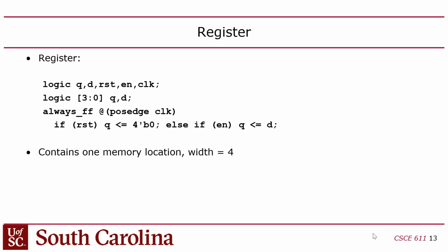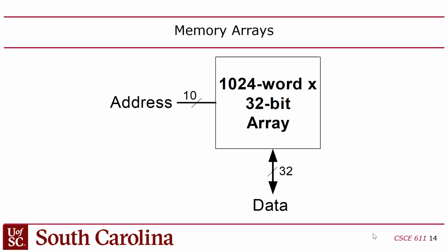Okay? But the switches are only 18 bits, and that register here is 32 bits, so you're going to have to pad it with zeros, unfortunately. Some students take the buttons, we have those buttons on the board too, and kind of piggyback them here. You can concatenate the buttons in the upper bits of this if you need to read the buttons as well as the switches. The lab sheet only requires that you read the switches. You guys with me? But you have 14 extra bits that you can tag along. Okay.